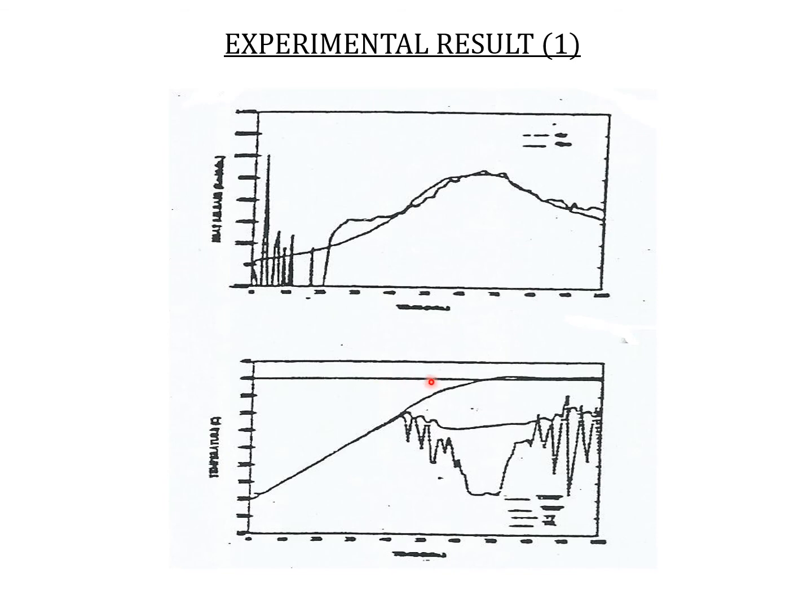This is the estimation for the Q and for the jacket TJ. Okay, the Q also has some oscillation, but slowly it tries to follow the heat release according to what the model is, and slowly the profile of TJ goes to what it's supposed to go, and then to get the TR to follow this profile. Okay, using GMC is not easy.